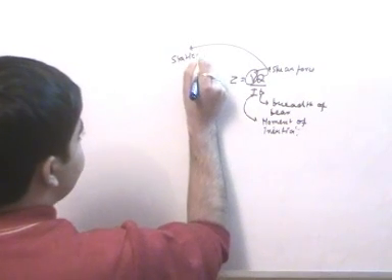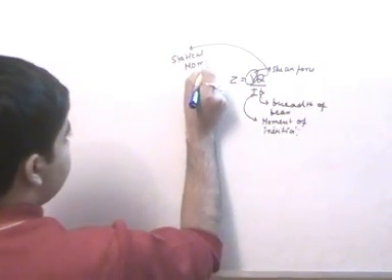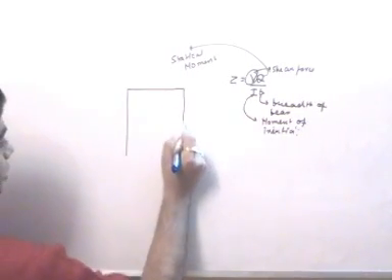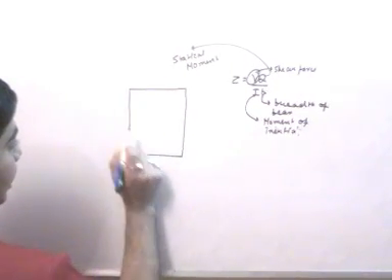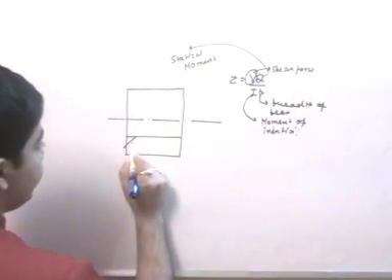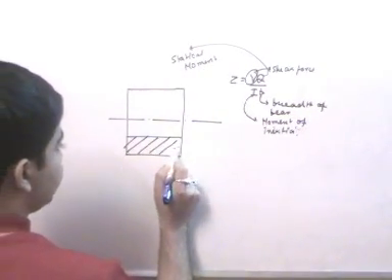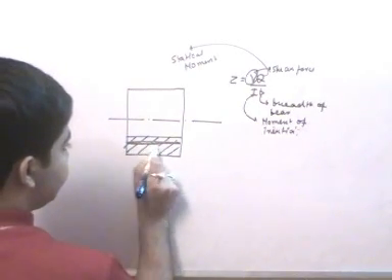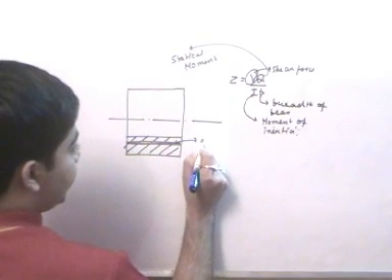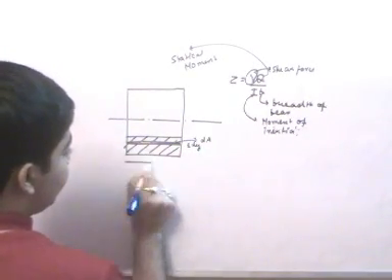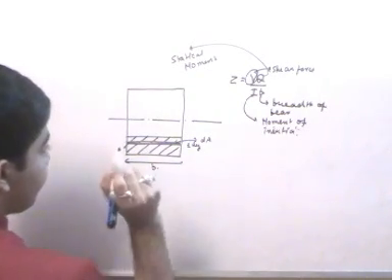Now what is the statical moment? Let us assume that we have some kind of a cross section like this, and this is my neutral axis, and I considered this elemental block, the shaded portion, and I considered some strips, and let this strip be of area dA and of length suppose dy and of breadth suppose b.